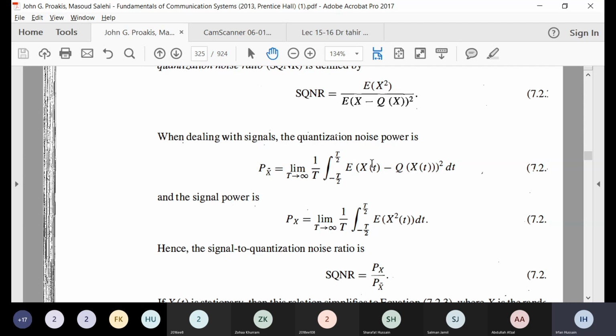So in case of stationary, we have learned in stationary processes that their means are constant as well as their autocorrelations. They are dependent only on the difference. So with all that consideration, you can very well see that for stationary processes you will be getting this equation, but if it is not stationary, then in general this will also work for stationary processes. But for stationary you can see that this will actually come outside the integral, and dt cancels, this becomes 1, so it will come out to be the same expression. This is the general expression, you can always use this, but no need to go into this complicated form once you already know that it is a stationary process.